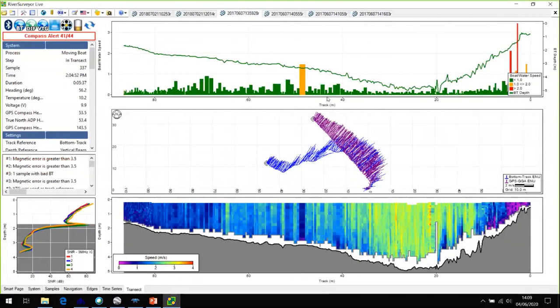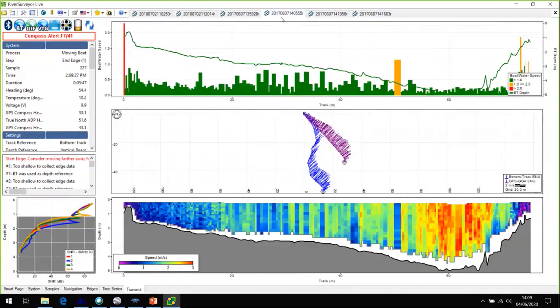Yeah, exactly. We're talking about moving bed, but actually, moving bed is one of the problems you can solve by using stationary mode. So it's very relevant to this, and Rob's quite right that when you do a moving bed test, unless you do the loop, which has its own problems, you're doing a series of stationary measurements. If you did enough of them, you can piece them together to get discharge. In the Sontek software, if you do the SMBA, the stationary moving bed test, it will recommend that you do a minimum of 3. And you do each one for 5 minutes.